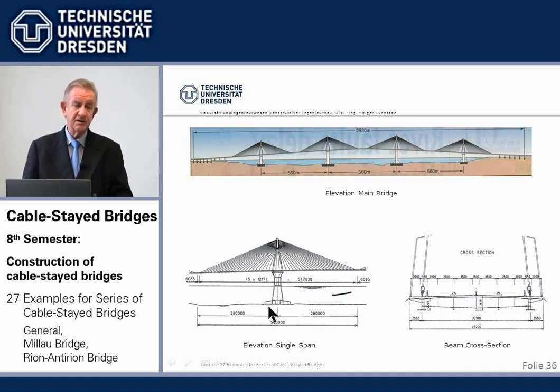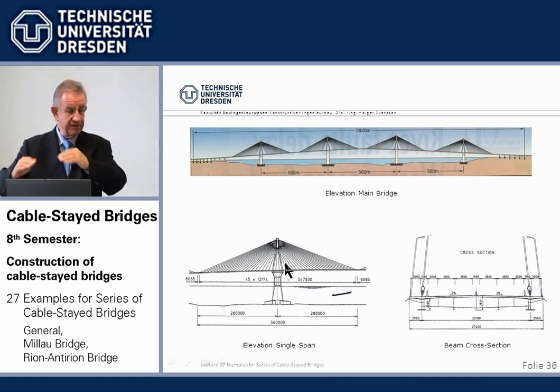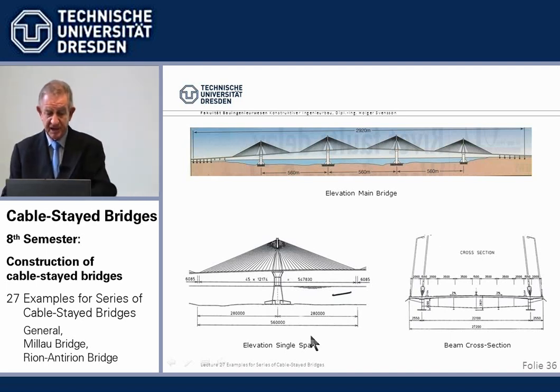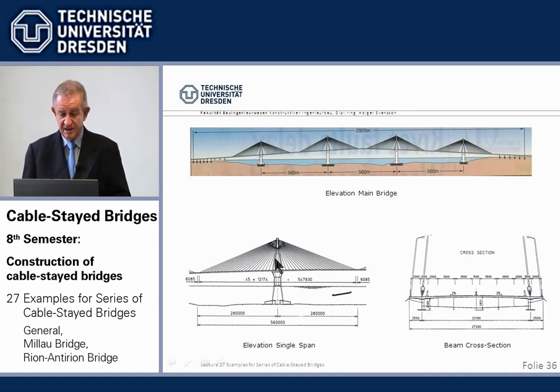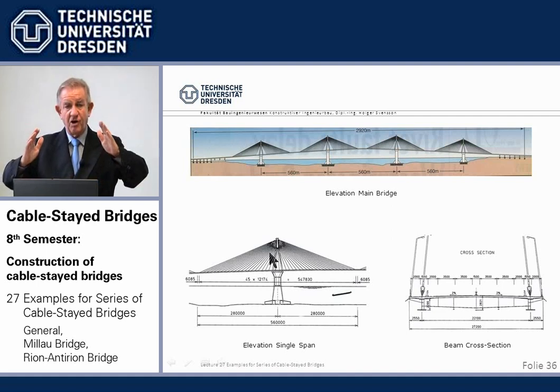And how now do we take care of our 2 main issues? Keeping the tower head in place and accommodating the beam movements. Keeping the tower head in place, we'll see it later also in some detail, we do in two ways. We have A towers again on top, similar as we had for Millau. In this case, it's a four-legged A tower, so it's transversely also A shape.